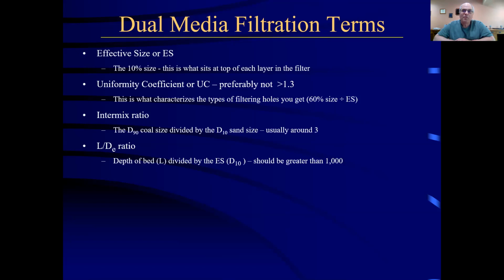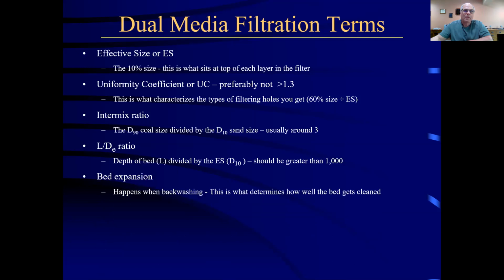If it doesn't, if you've lost media over years, your number is going to creep down to 1,000. At that point, you should think about replenishing the media in the bed because you can't filter too well after that. Bed expansion, that's the term we use when we're backwashing.